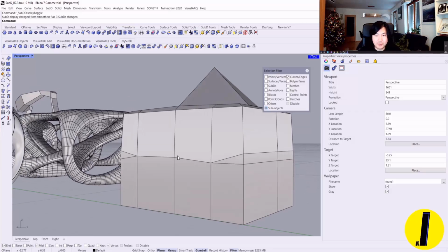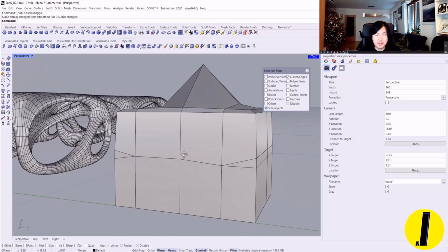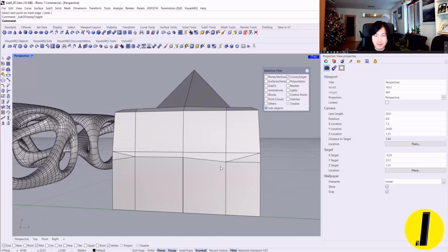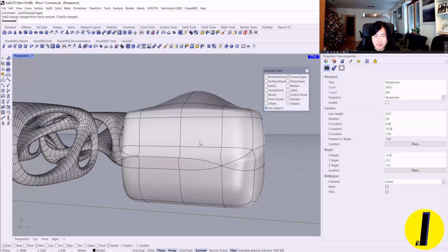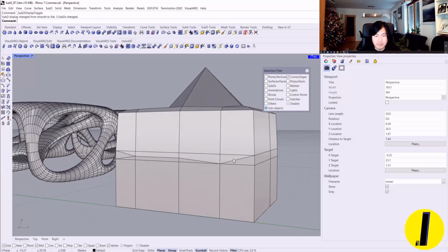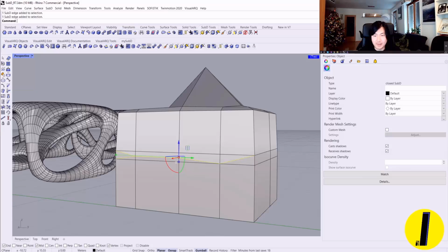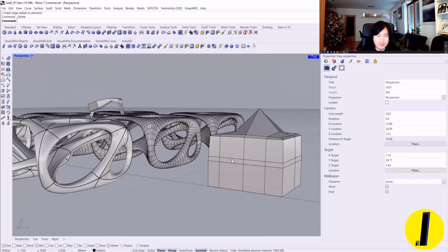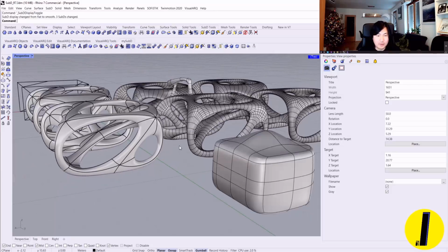But it's kind of a funny situation, it's good to avoid this sort of situation in polygon geometry. So let's see what we can do. We can insert these vertices between there to there. Then yeah, it's a bit better. We can also do it again here to there. And, you know, we can delete the rest if you don't like it. We can select the rest and the delete command would work for you. So I'll just select them and I can delete. Then we can keep the geometry here.